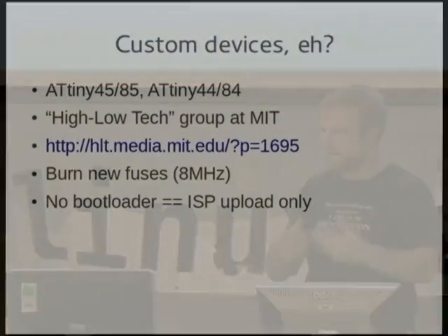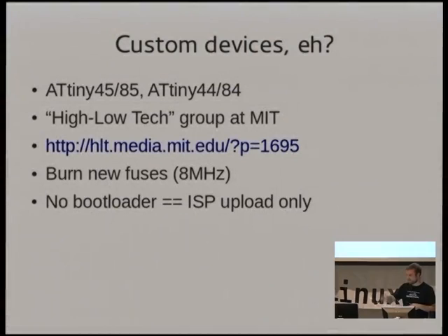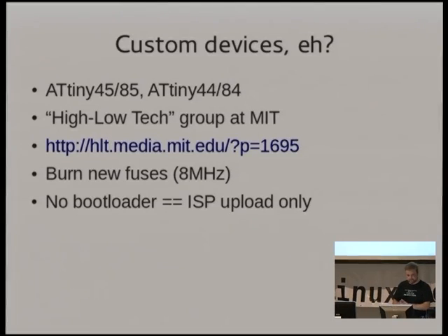Word of warning though, if you get them wrong, your chip may not boot until you actually get the right hardware around it to make it work again. If you burn a fuse that says this requires an external crystal, it won't boot without one because the clock counter for the CPU actually never advances. And that's the reason why you can't just take a chip out of an existing Arduino and try and run it in a breadboard without a crystal. Because you can't have a bootloader on the really, really small devices because of the limited amount of flash they have, you absolutely have to do an upload with an ISP.